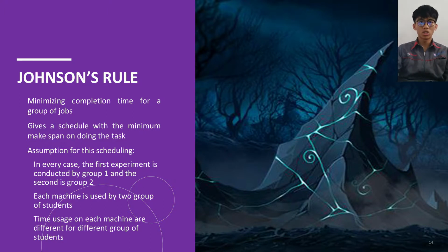And then by using Johnson's rule, we are able to minimize the completion times for a group of jobs to be processed on two machines or 2 work at a time. So we are able to minimize the total idle time, resulting in better customer service levels, and also simplicity and inherent fairness. So the due date will be addressed, and the tardiness will also be minimized by using this Johnson's rule method. So that's all for the methodology that we use.